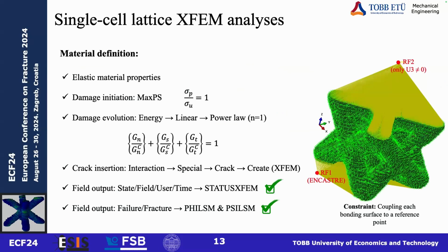Some points about XFEM analysis. For material definition, we use elastic material properties. For damage initiation, we use maximum permissible stress and this equation. And for damage evolution, we follow this chain and we use power law equation with n equals 1.